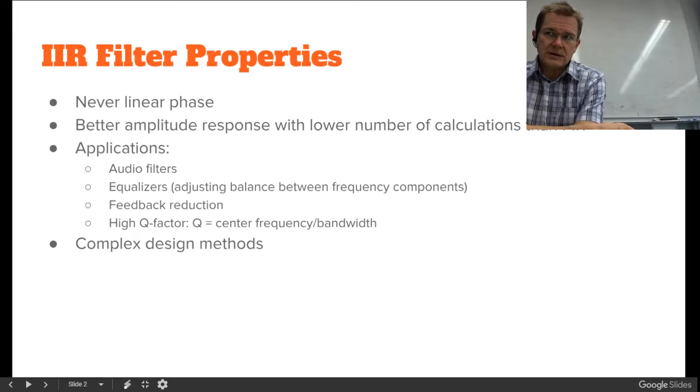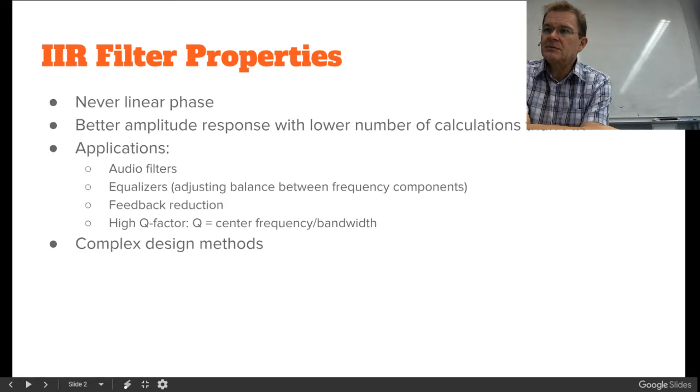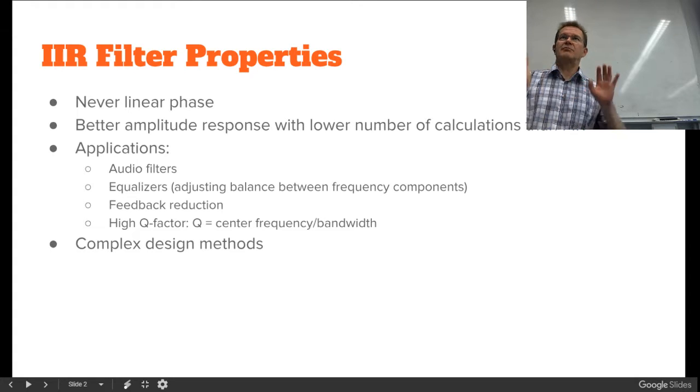The caveat on the IIR filter is that it has a little bit more complex design methods. On FIR, we have the windowing. You can still do it by hand. On IIR, well, it's back to the engineering tables and that kind of stuff, or tools. However, we have free tools available for anyone to use on the internet. It's full of them. Usually, some universities have put them there.